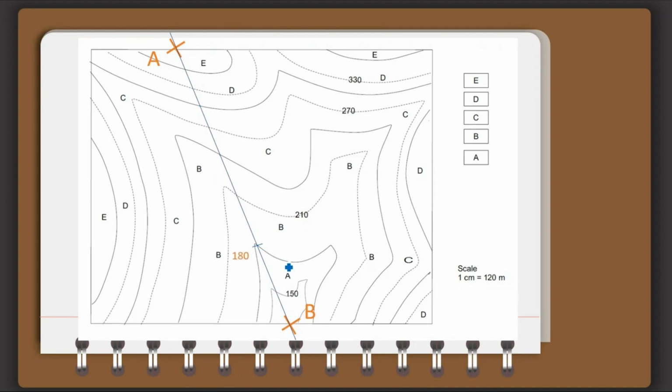So what we have to do is go for an interpolation method, because this is the value of 210, this is the value of 150, measure the distance, and this represents a 60 meter variation, and then measure the distance of this and convert that to meters. Okay, so this interpolation method we can adopt here, but for the time being I am assuming the values, because the value is almost the middle of these two values, 150 and 210.